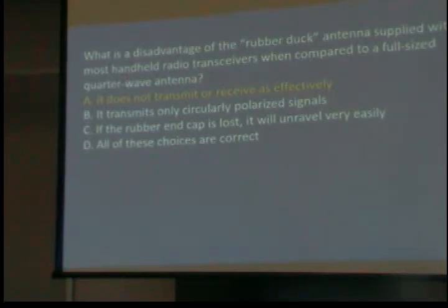By the way, with homeowners associations, there is a negative to doing this because you're putting it close to vegetation. But I've actually built a half-wave dipole for a guy, which is 38 inches long, in a piece of PVC with a center feed, and we hung it in an arborvitae. And in Lancaster, he was hitting, I think, 20 or 21 repeaters.